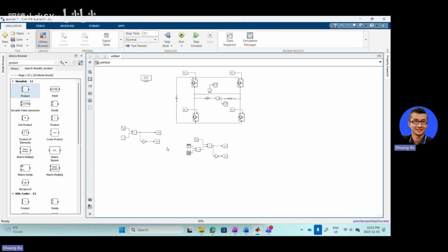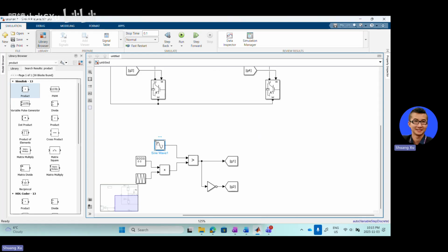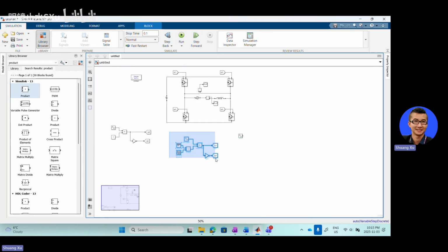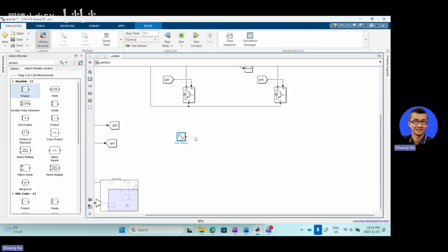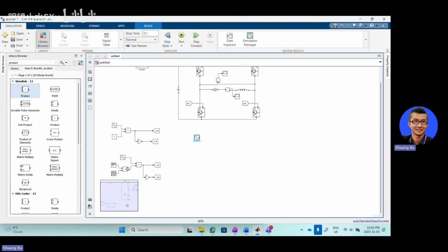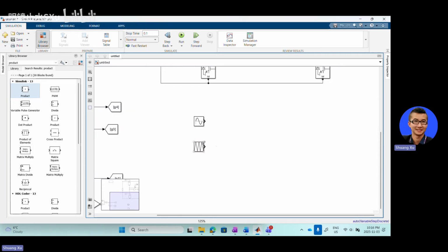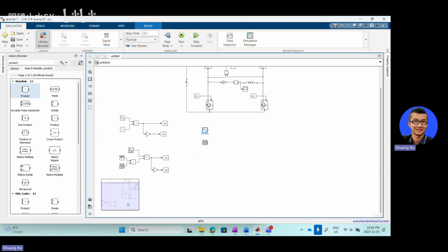Then we will continue with the bipolar SPWM. If you remember, as we discussed in the class, the bipolar SPWM actually has an easier modulation technique because we only need one. The left hand side is unipolar. For the bipolar, we just need to use one reference compared with one carrier waveform. So the reference will be the same. We do not need to change it.